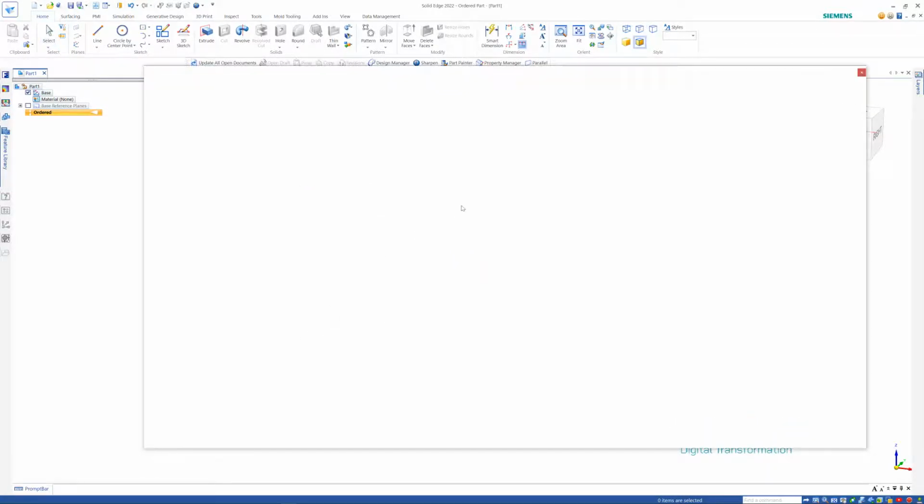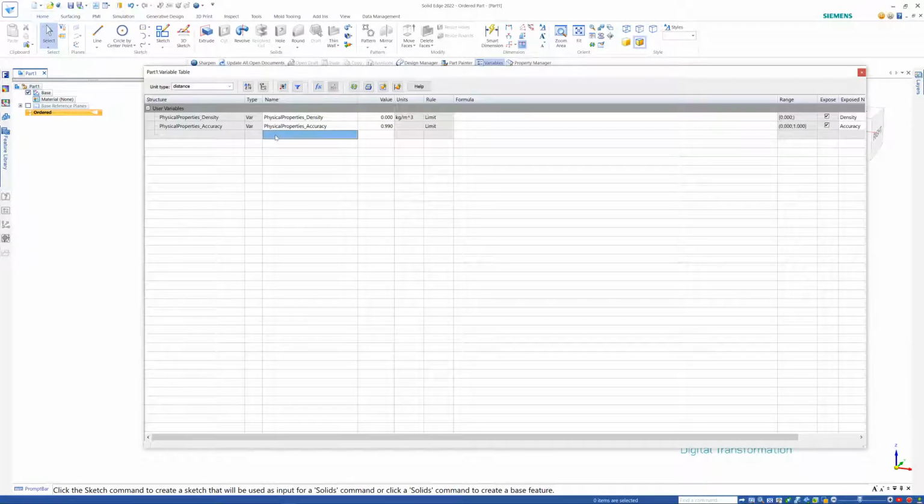And then we're going to go into our variables table, and we're going to set up a variable here as size. So that's going to be our size. I'm going to start with 15mm, and that's going to be the size that I want on there. And then I'm also going to have length as well. So length is going to be size times 10. So that's going to give us our option on there for our formula. Okay. So now we can put size and L in there.